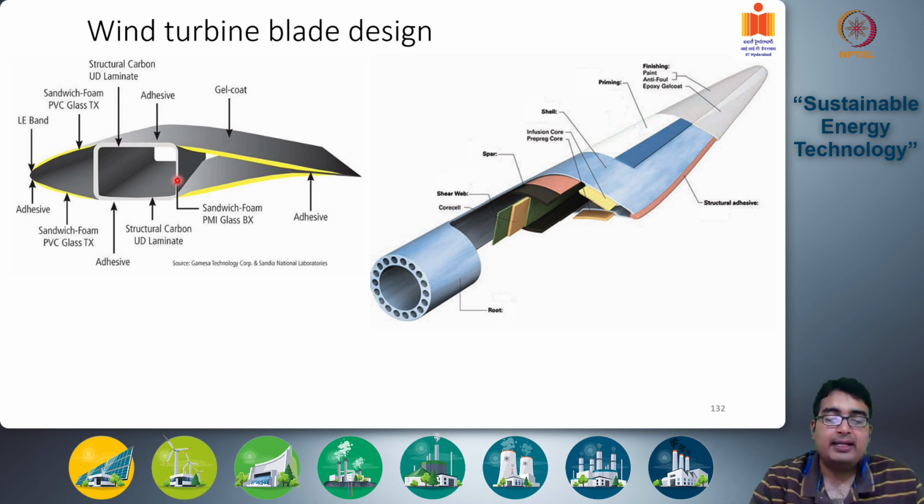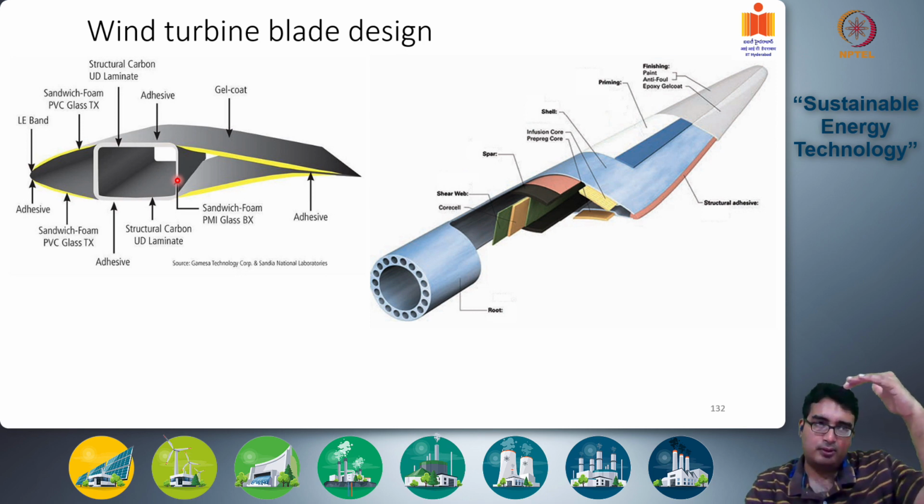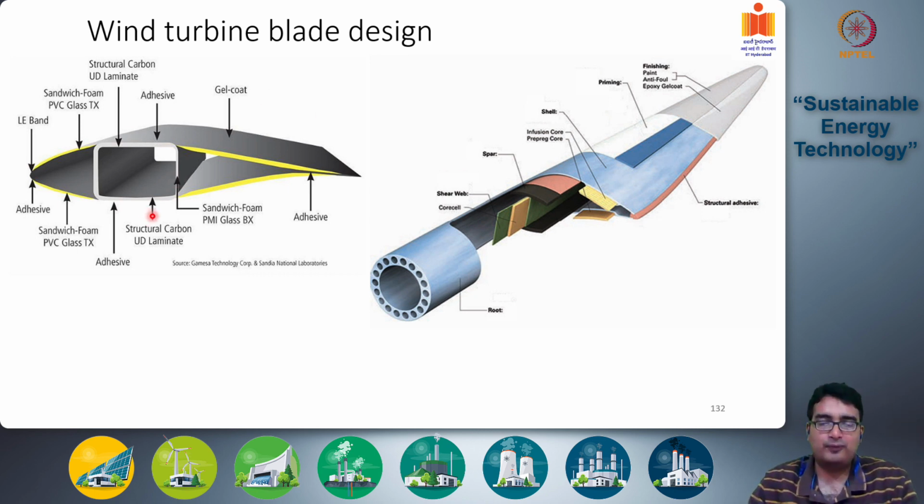This is because of a pressure imbalance between the upper contour of the aerofoil and the lower contour of the aerofoil. The wind or the fluid is accelerated over the upper contour and decelerated over the lower contour.